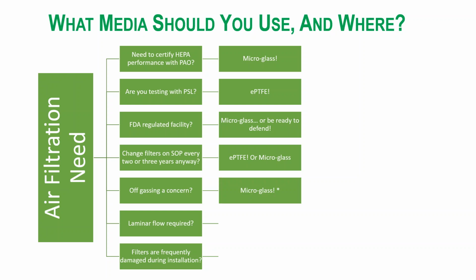Is off-gassing a concern? The reason why I highlight this is because of testing methodologies. Microglass is tested with PAO. We know that. And as a result of that, you know what you're getting when you purchase a unit that's been tested. The problem with PTFE is that in many cases, it's certified with other reagents, not necessarily PAO. In some cases, triethylene glycol, for example, has been used as a test reagent. It's used in China.